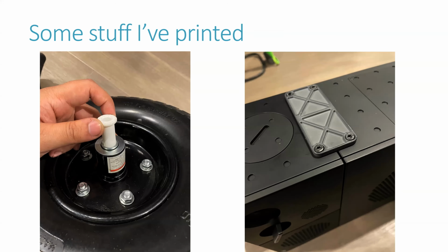Rob, I don't know if you have anything to add on metal or if you're interested to try anything. No, I do have some experience with metal 3D printing, mainly the offering from Markforged, where they use FDM technology to print stainless steel. But like you said, that is pretty expensive stuff, not very accessible. You need an industrial environment because you need to soak the parts and keep them in an inert gas to keep them from oxidizing. It's really complicated, so I haven't done it yet. I am very interested in trying to cast some stuff. So stay tuned. Maybe I'll try it out.